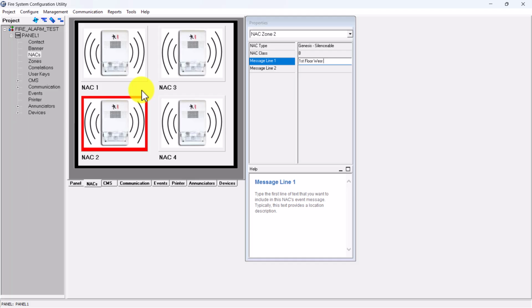So we leave it at this point type. Let's say you're testing a tamper switch and you hit the lever and you hear it beep, okay, we know that it went active, and we know that when we get back to the panel, if we set the tamper switch back right, it will be clear. So let's label the rest of these devices.